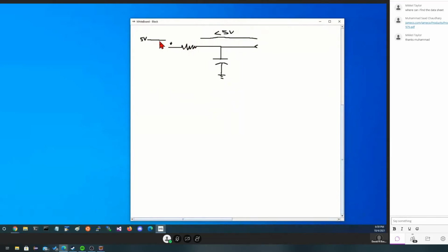Now let's assume that I drop this to 0 volts. It's no longer 5, it's now 0. Well, what's going to happen right here? Well, this had 5 volts and there was a little bit of a drop here. But doesn't that mean that the top of this capacitor must have also been 5 volts? Sure it does. I said we're going to come back in a while. In a while, if this is less than 5 volts, this will be whatever that number is. But if I drop this to 0 volts, shouldn't I see this drop and then this go? Well, we can't go negative because we don't have anything that will supply negative voltage, but this could go to 0 with no voltage drop across this.